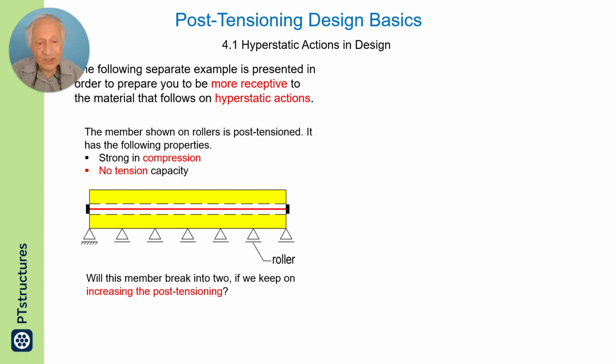It is an extreme representation of concrete, with the difference that zero tension capacity is the property. Assume that it is supported on simple spans, rollers all along except the end, has a post-tensioning tendon through its center, pulled and anchored.